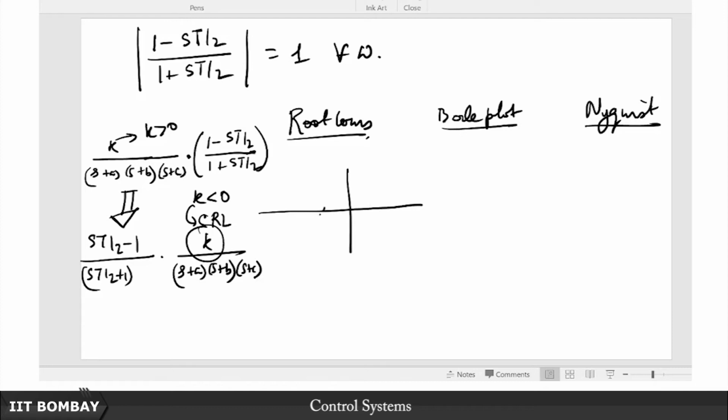So we have these 3 poles here, and this additional pole due to the time delay like term, and a symmetrically placed zero like so. Now we know that in a complementary root locus the rules change, and therefore you will have the root locus existing here, here, and here. So that is one thing for starters.